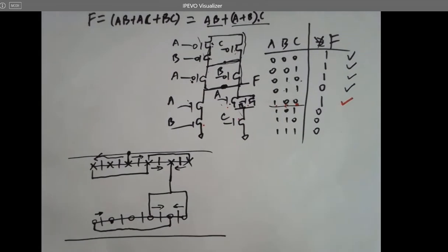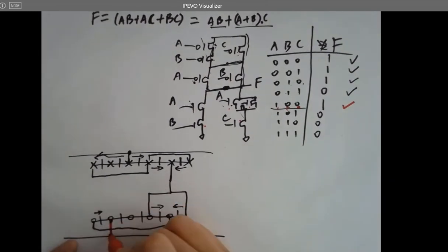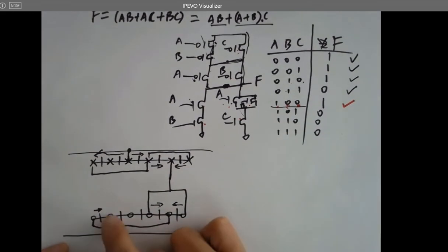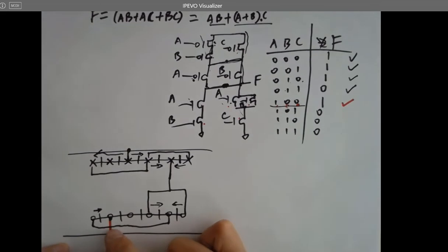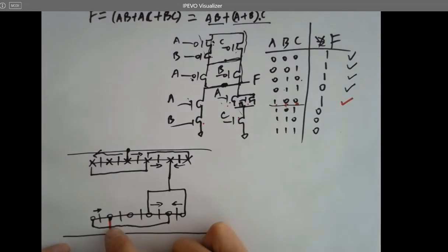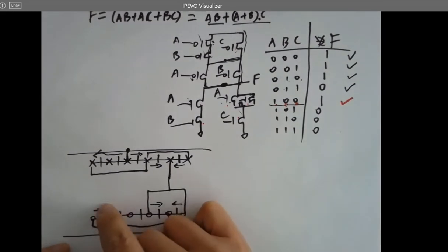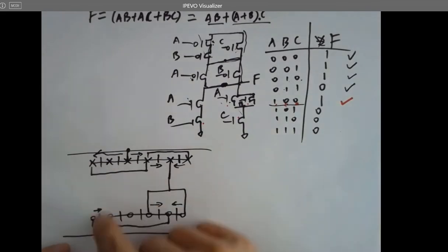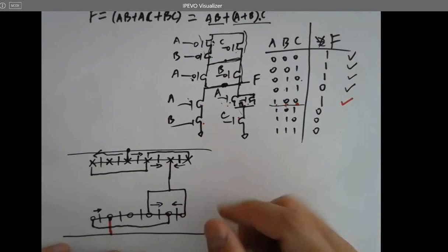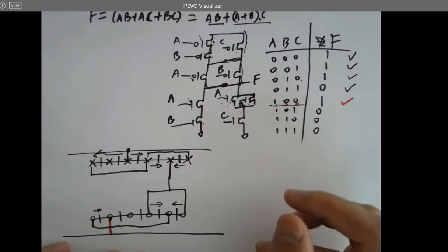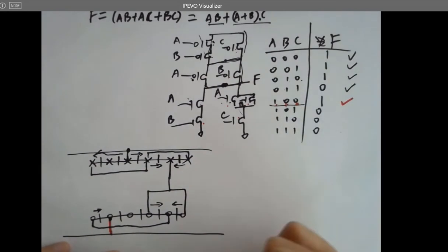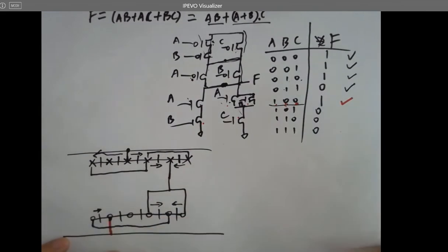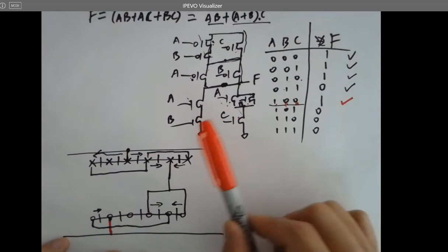This node. Ground, right? So you want to be careful about it because they are both metal ones, and you probably have to find a way to get around this line. You can go up and go down, but anyway, since there will be a lot of traces in the middle, you have to find out the vias, get into metal 2 or even metal 3 to not short these circuits. I'm just drawing this for us to understand this easily. I don't have too many colors of markers.